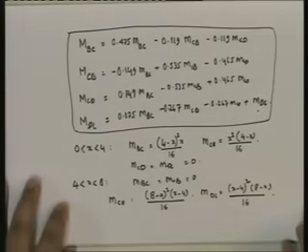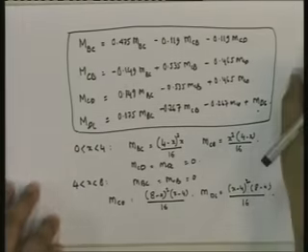Okay, so these are the fixed end moments, and now we need to do what's the next step. Once we have figured out from the moment distribution the relationship between the member end moments and the fixed end moments, we also have the expression for the fixed end moments while the load is traveling from B to C to D. And now finally what we have to do is write down all the expressions for it.